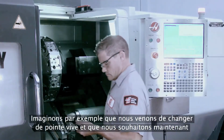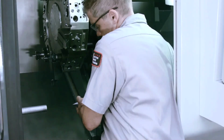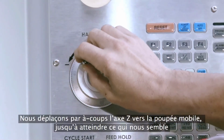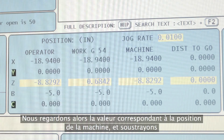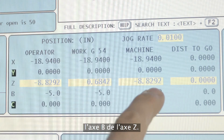Let's just say, for example, we just changed to a different live center, and now we want to increase our setting 94 clearance value. This is how we would do it. You jog the z-axis towards the tailstock until you reach what looks like enough clearance. Then we look at the machine position value and subtract the b-axis from the z-axis.